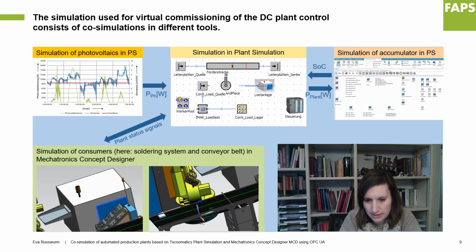It's a PLC, and to simulate the PLC, we use PLC Sim Advanced. So the PLC is defined in TIA Portal, and the project of the TIA Portal is loaded to PLC Sim Advanced, to a virtual controller. And the virtual controller controls the behavior of the power supply for the whole plant.